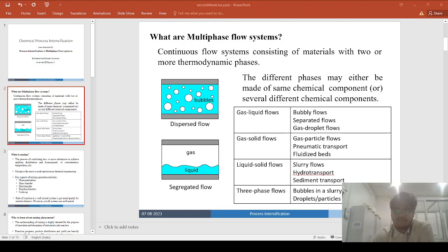So in the case of a microreactor, the environment provides an extremely uniform structure. This extreme uniformity of the structured packing arrangement provides very high control over the fluid flow, and that greatly enhances performance relative to the micro packed beds. And the activity is greatly enhanced if the catalytic component is supported over a porous layer formed by making the silicon posts porous. So those silicon posts can be made porous.